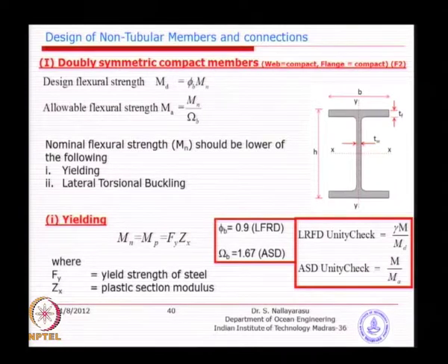As you can see, when you calculate the properties, you will find the flanges are kept away, so you will get a higher moment of inertia. So you can give the notation major axis bending, and predominantly these beams are placed as floor beams in this fashion; nobody goes and turns them.